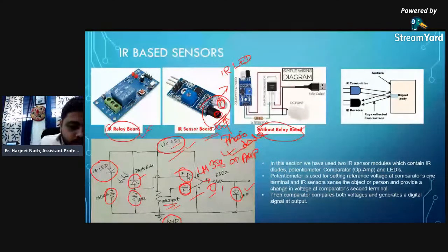Before this LED, there is another resistor, a 330 ohm resistor, which is basically used to protect this LED, because we know this LED basically works with 3 volts power, and as we are giving 5 volts over here, that may damage this LED.